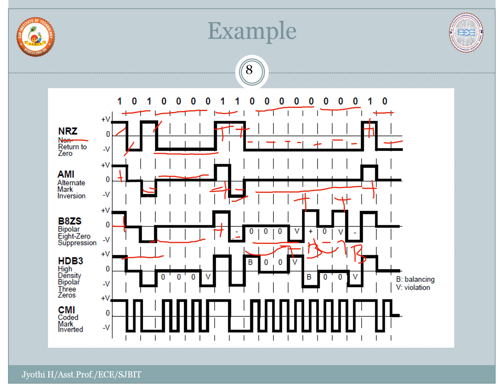Whereas HDB3 comes into the picture when there are 4 consecutive zeros. So here we are receiving 4 consecutive zeros. Earlier we considered an odd number of 1s, so the coding is 00V, which is going to follow the earlier polarity. So next it becomes 1, next becomes 1, it is positive, negative, and since it is an even number of 1s before the consecutive zeros, this code becomes B00V, and here it is B00V, and the next one becomes positive and it is 0. So B00V, it is positive. Here you can see earlier it is negative, this is going to be positive, and V is going to follow B because it is violating the rule of bipolar.